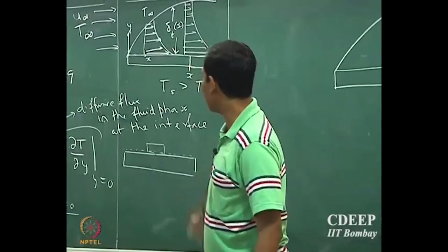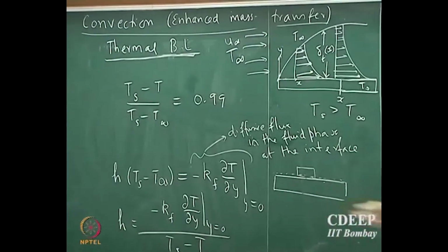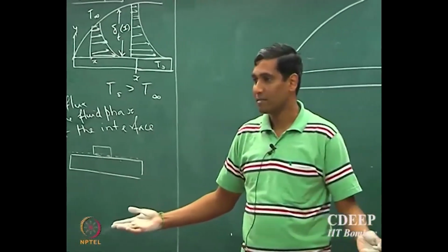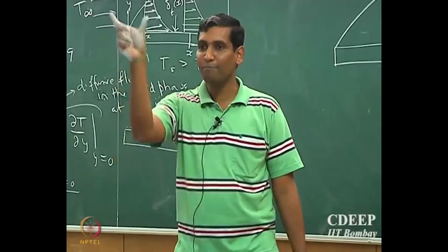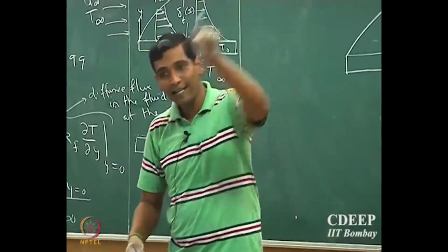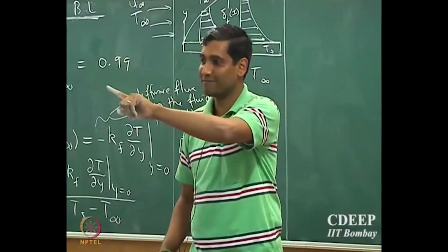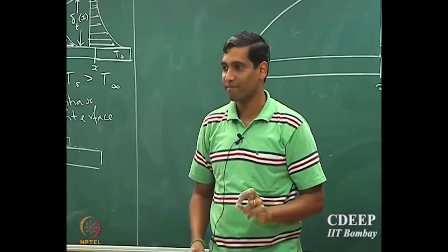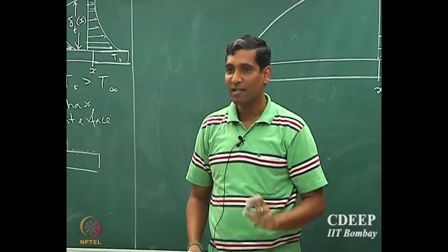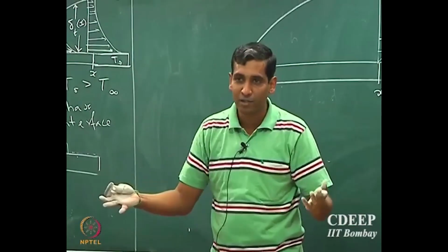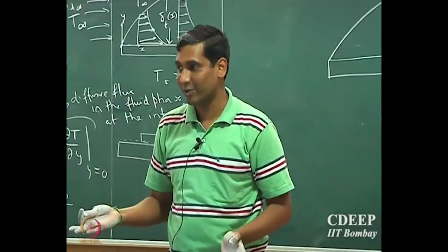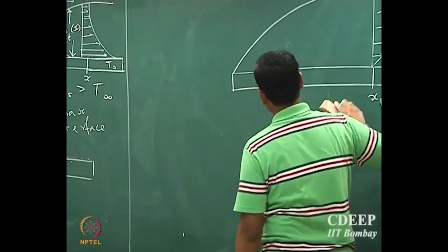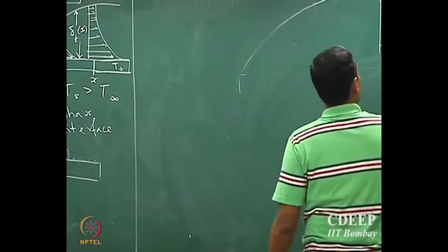Oh sure, steady state doesn't mean that it's not flowing. You can have a steady velocity, right, where the fluids are moving at the same bulk velocity. So remember that even for a simple 1D slab, in a steady state you had a linear profile. The temperature is not constant. So steady state does not mean temperature is constant, it's the temperature profile which is constant. So therefore gradients are not necessarily 0 when it is a steady state. Of course there can be a system where gradient is 0, but that's not always the case.